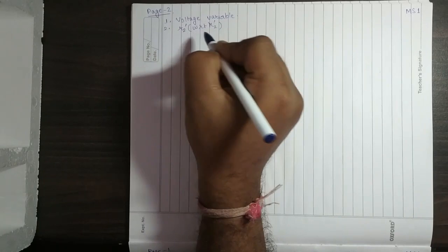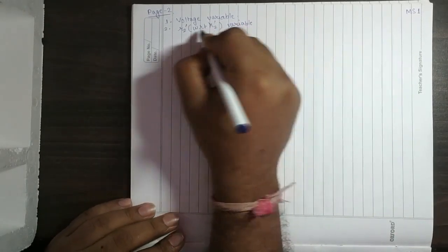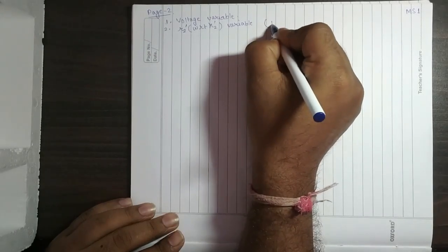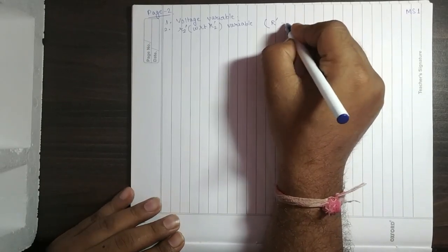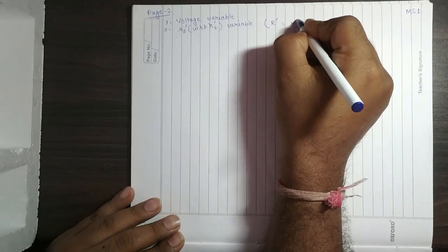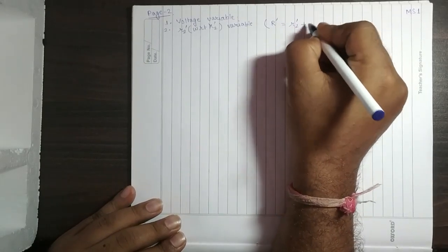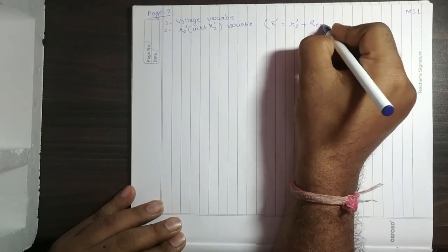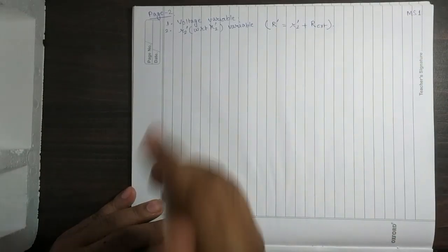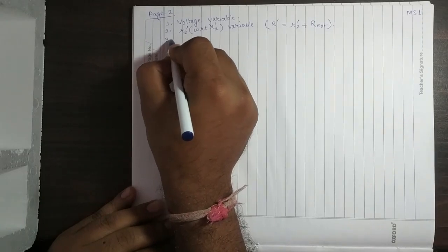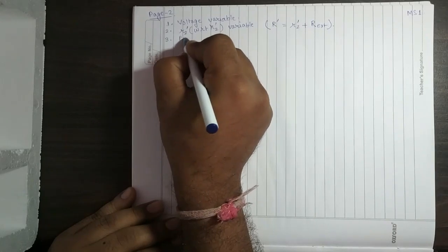This one effectively means that you have got some resistance R dash, which is the combination of R2 dash, that means the resistance which is already in the motor, plus some external resistance, this total. And the third one is variation of frequency, that is frequency is variable.